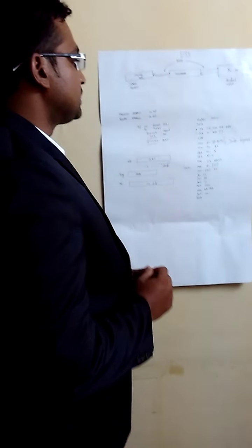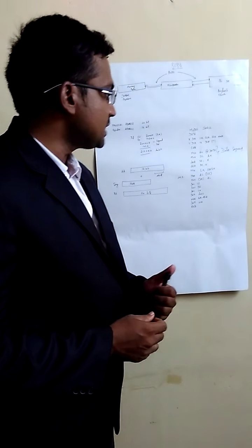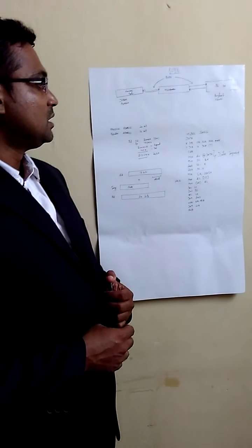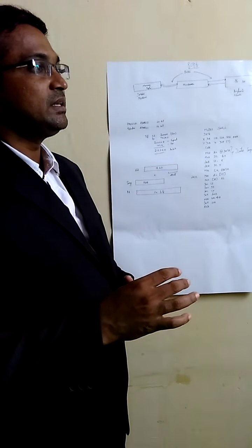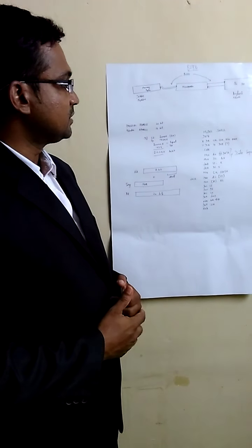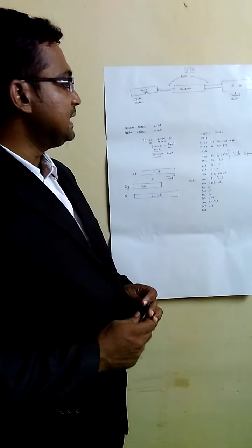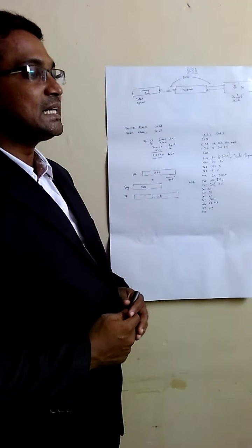The data segment register is initialized by MOV AX, @DATA by the immediate addressing mode, and MOV DS, AX. Now the accumulator has the address of the data segment, that is the X value. After that comes the instruction LEA, load effective address.